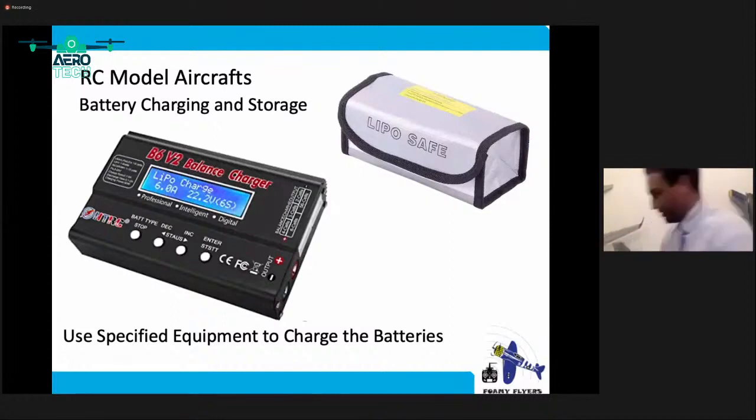And the other thing I want to show you is this, which is actually a battery cell checker. If you are out in a field and you want to know whether the battery levels are good, this helps. Normally with normal batteries, we use them until they drain out. But for LiPo batteries, you cannot do that. You need to have a bit of power left, like 20% of the power left on the battery. If it goes beyond that, it will damage the battery.